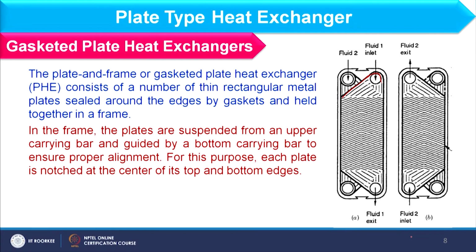And if you consider these notches, here we have the notch. These notches are basically used to hold the plates. As I have already discussed, a frame is used where these plates are hanging. So, hanging means what? It is basically fixed with these notches. Wherever required, the plates can be removed, cleaned and placed again at the right space. So that is with the gasketed plate heat exchangers.